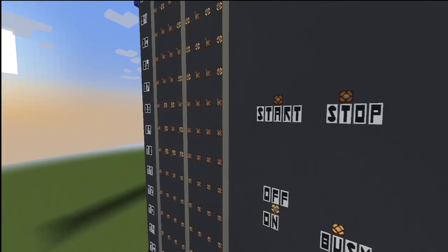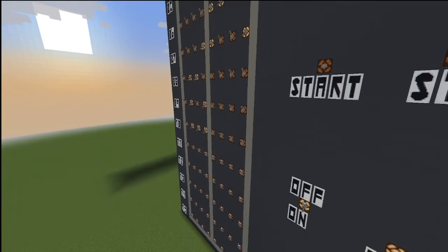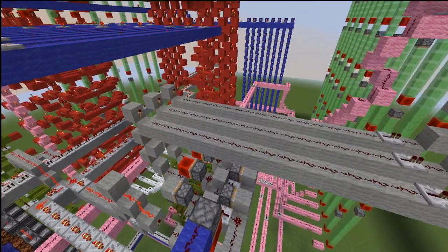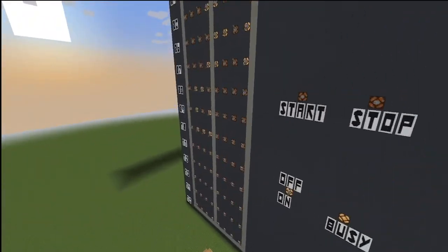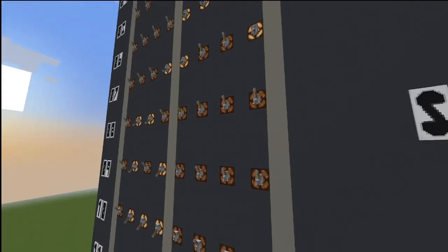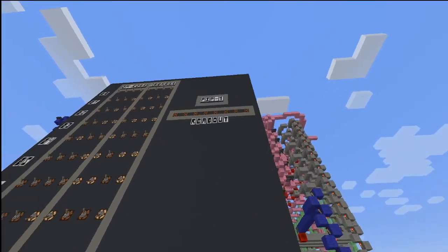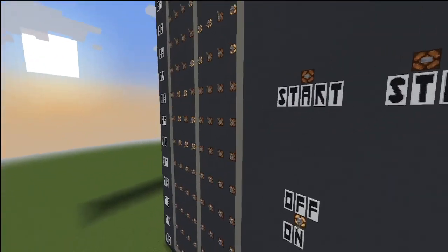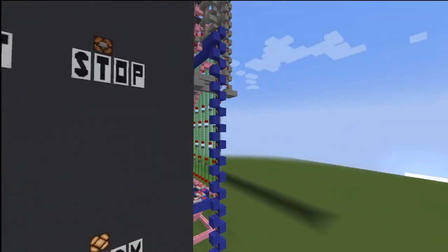And so we're right here at the no operation on line 8, and it's going to run next the out and then the halt. So if we look where we're at, we still have a little bit, so I could get a better look at that. So it's almost done with the no operation here, and then it's going to run the next one, which is going to be the out, which is going to put what's in the A register, which is currently 15, to the C register, which is directly linked to the readout. And then here it's going to stop the clock with the halt.